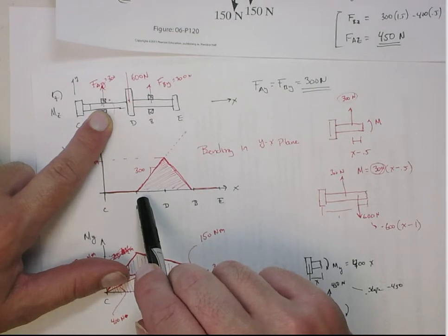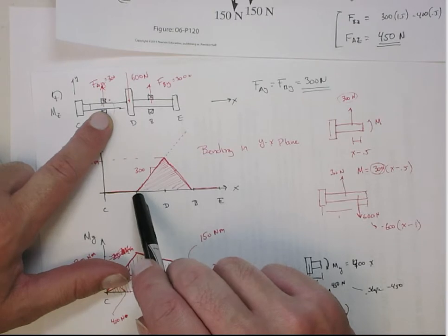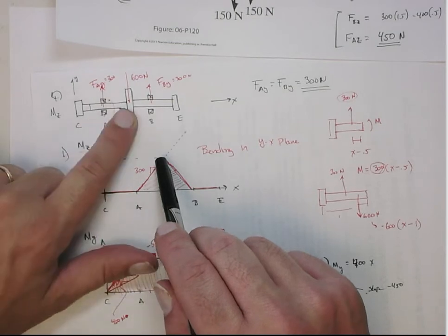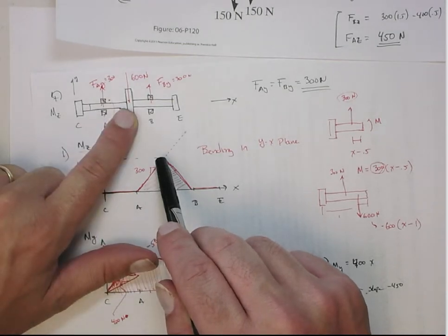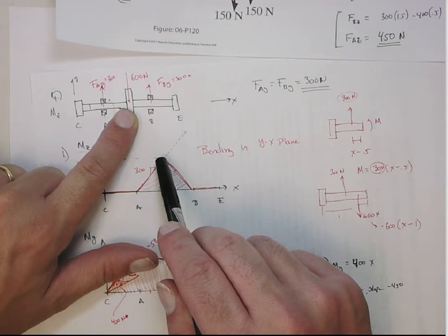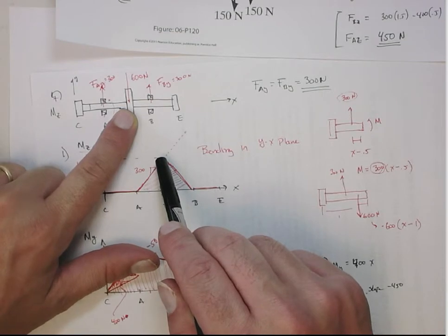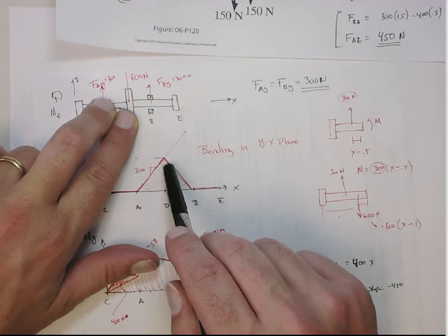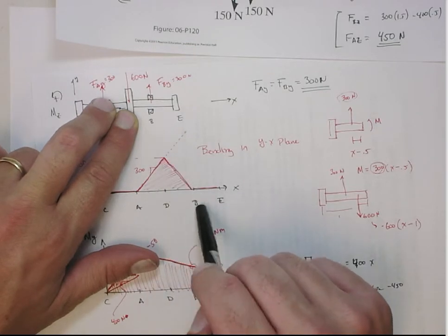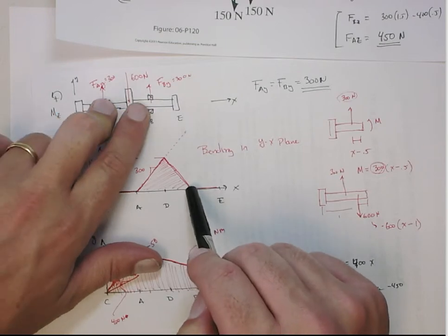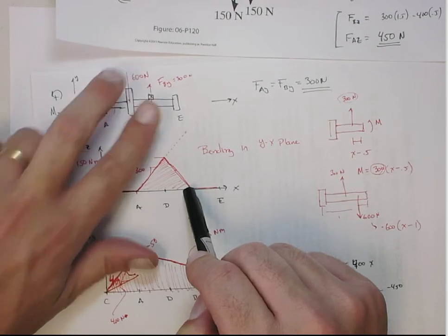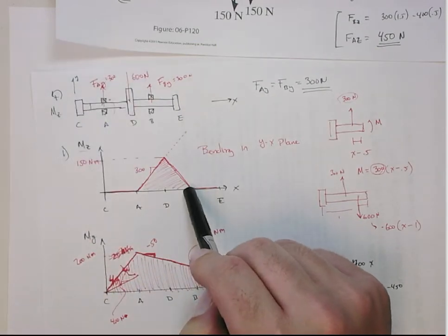You have to check the sign, whether that's going to be a positive bending moment or a negative bending moment. In this case, it's a positive bending moment. It has a slope of 300. So it goes in that slope of 300 until we get the effect of the 600 Newton point force. That's going to give me a minus 600 plus a 300. So the net slope is going to be minus 300 until you get down to B, at which point from B to E, the net force is going to be 300 plus 300 minus 600. So that's 0. All right.